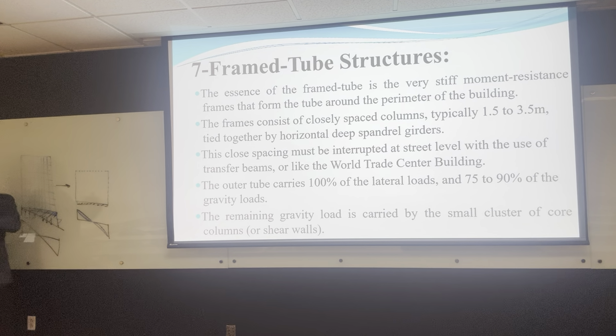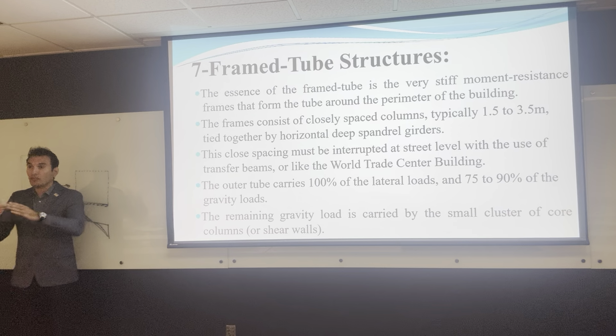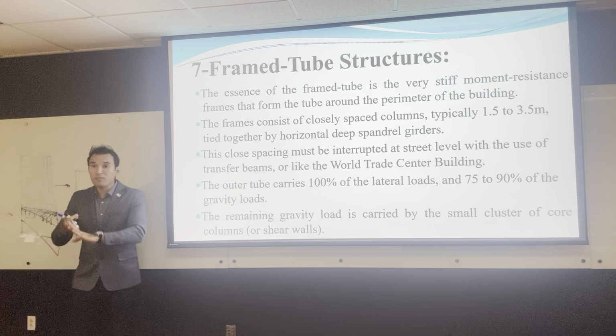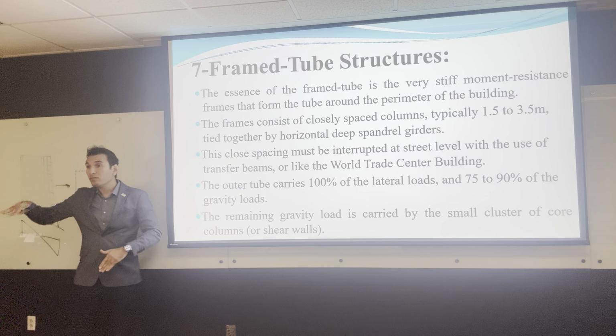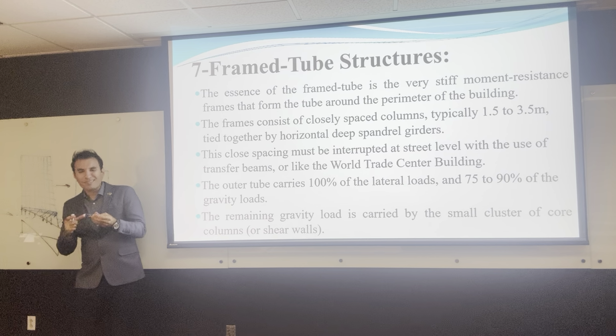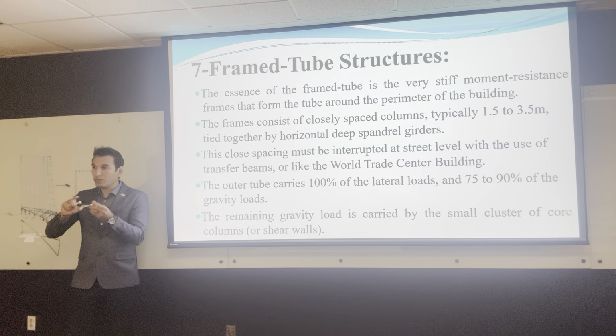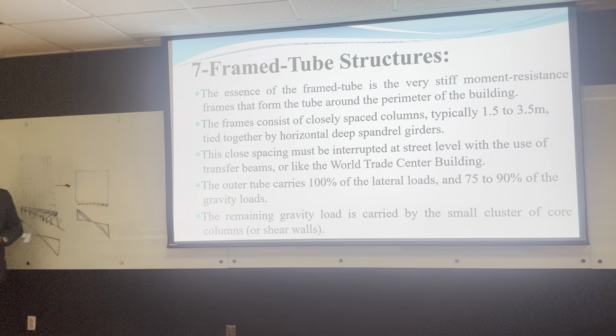What if we increase the column dimension, not the spacing? You can increase the column dimension, the column spacing, the beam dimension, so we can play with all that. The beam width can help a little bit, but not much. Mostly the beam depth is what helps with this. So that's about the frame-tube structure.